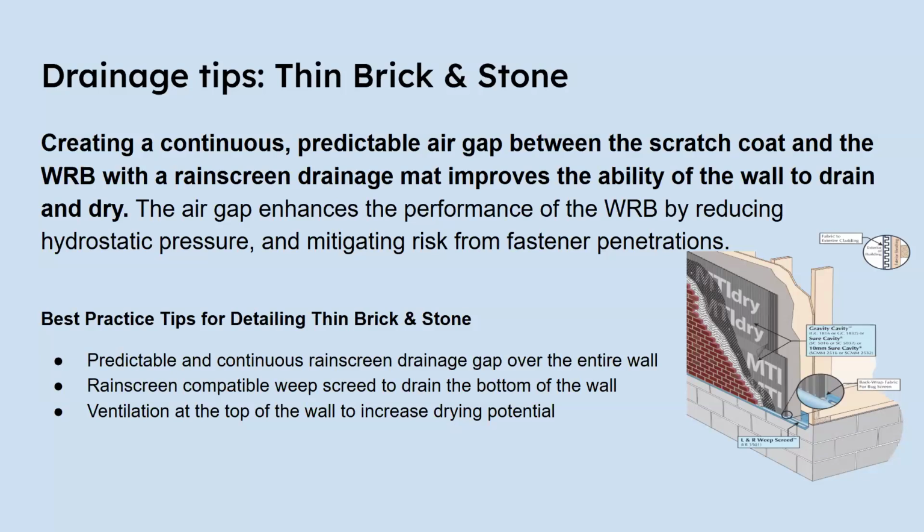Not going to do as good a job because that allows the cladding to pillow or settle into these gaps between the strips. Best to use a continuous drainage mat with a continuously thick or wide gap.